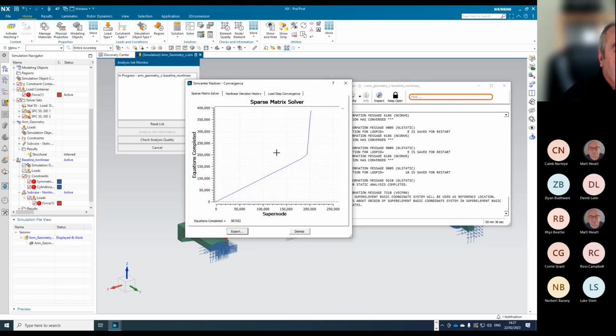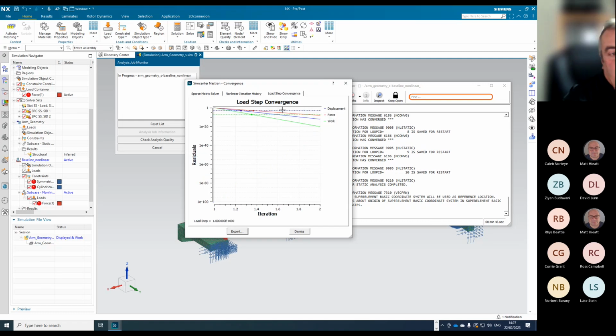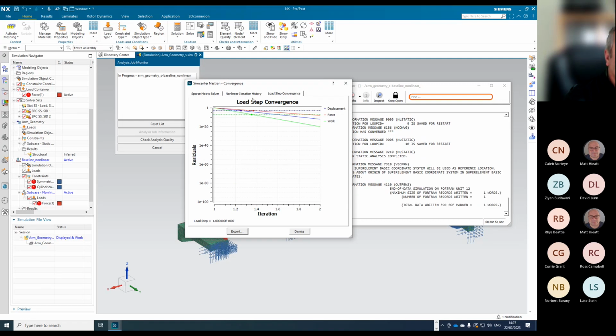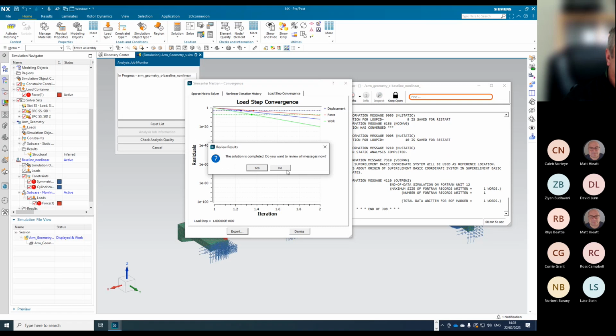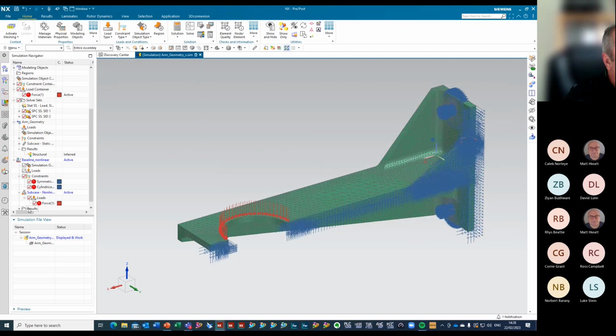It's gone from 0.1 all the way up to 1 second. That's quite common in a nonlinear solve, that you see how something is converging. Here we can look to see how each time step is converging, and how that affects our nonlinear progression to a solution. Okay, so it's solved. Didn't take too long.